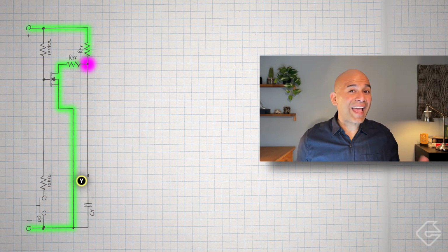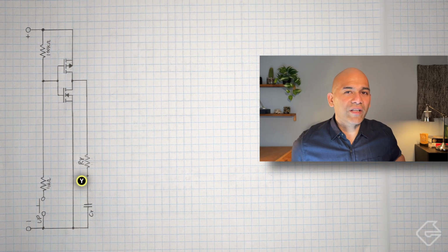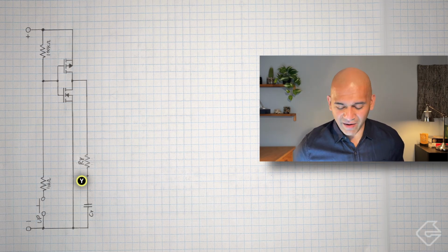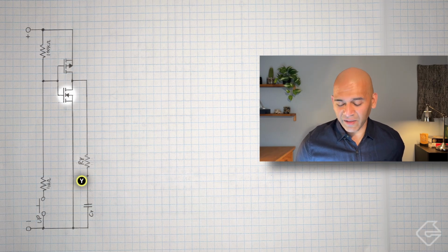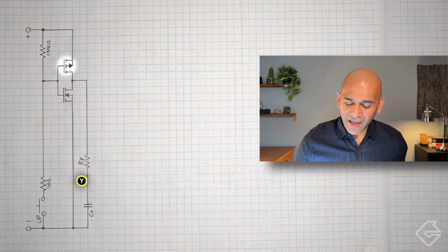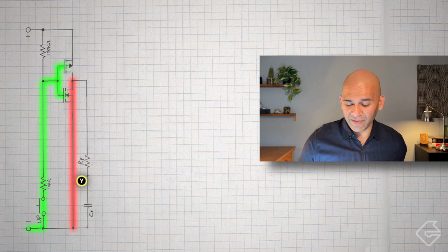So there is something else that we can do to resolve this situation. Here's an alternative setup that will get us what we want. Rather than using a single MOSFET, I've used two, a complementary pair. This is the N-type MOSFET that you're all familiar with, but over here is a slightly different beast. This is a P-type MOSFET, and functionally it's kind of like the opposite of an N-type. And when you put it into this configuration, when I press this button, just like before, this position is going to be 0, and this MOSFET is going to be disengaged. So the discharging path is now removed.